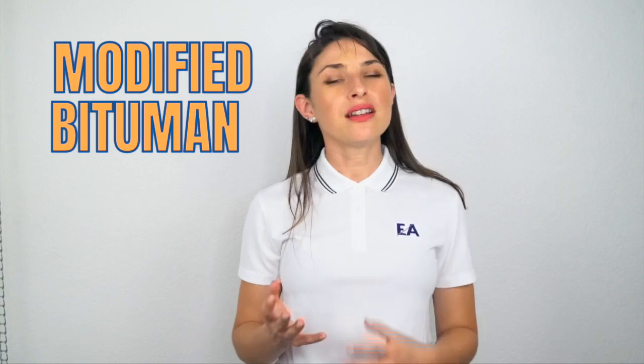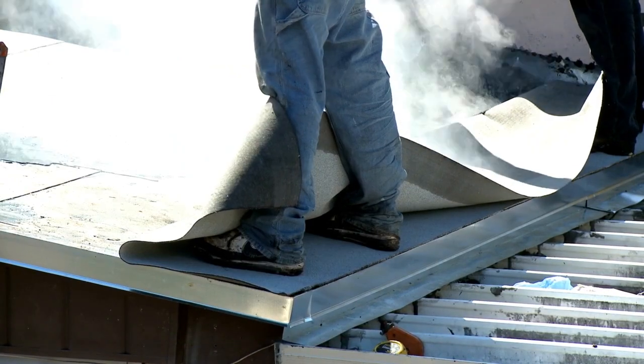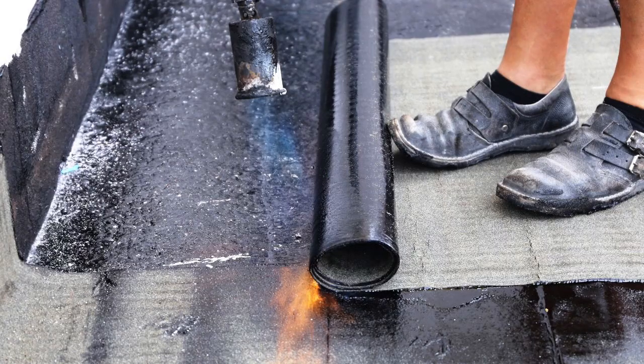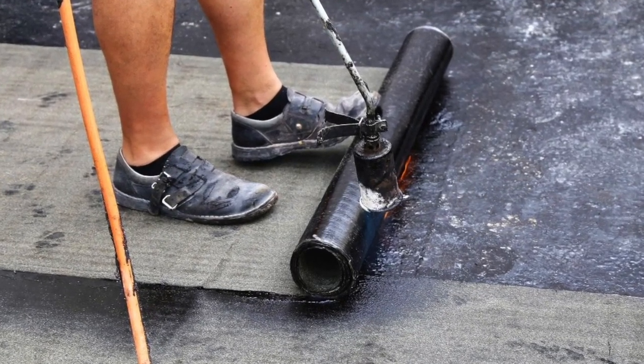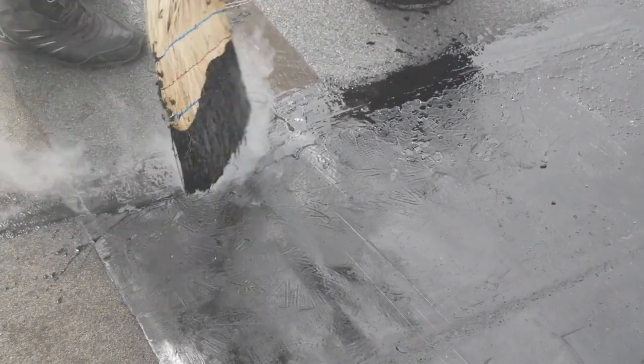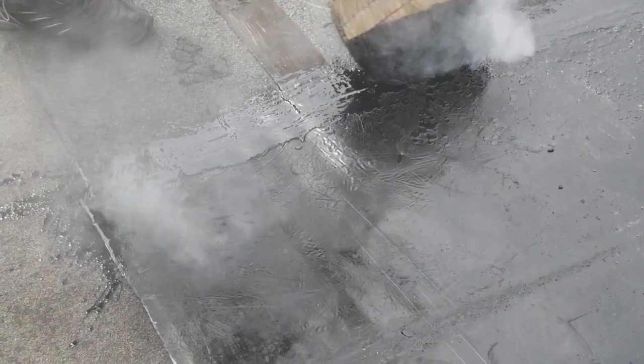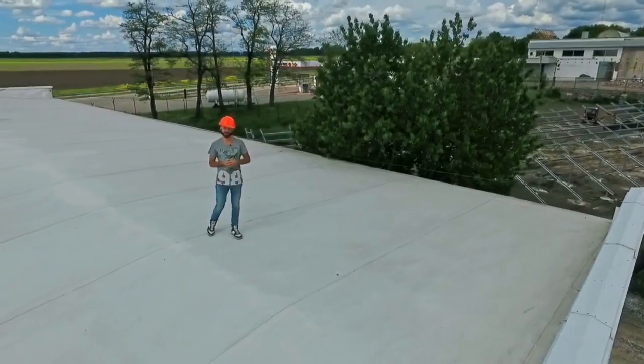Installation. A modified bitumen roofing generally consists of 2 layers, a base sheet and a cap sheet. Modified bitumen is very similar to ice and water shield. The base sheet is often self-adhered and the cap sheet is torched down to be fused together to prevent separation. It is designed to be flexible, which helps the longevity of the material, especially in extreme hot and cold weather. It is easy to install and you can layer it on top of old materials.